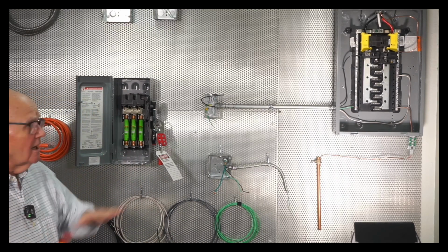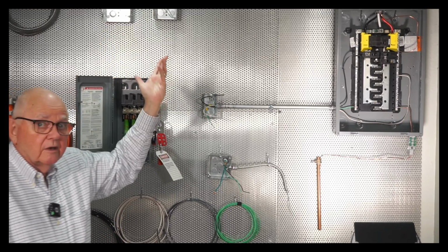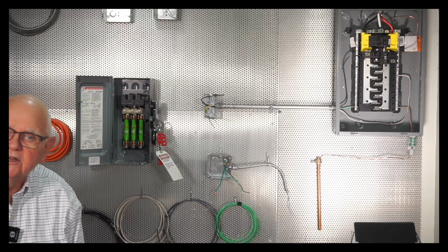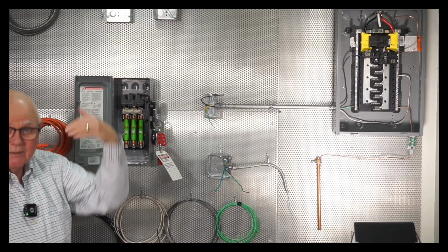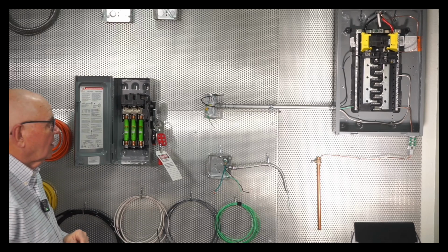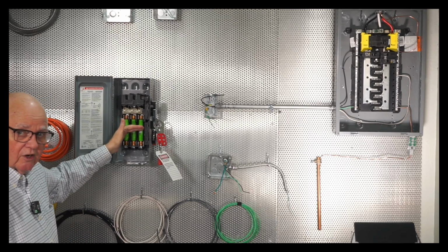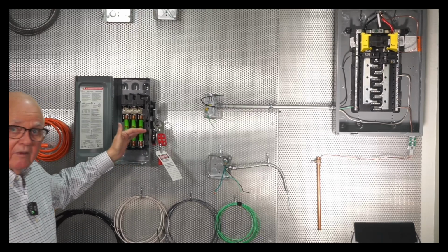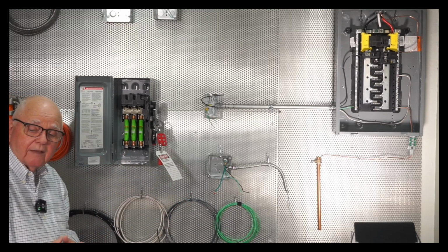The conductors that come into the top of my disconnect switch, probably coming from a switchboard or maybe a motor control center or whatever it is, those are called feeder conductors. Feeders, and that's a separate article, isn't it? Separate article in Chapter 2. But the branch circuit runs from my final overcurrent protective device out to my motor, whatever motor I've got coming off of these 30 amp fuses.